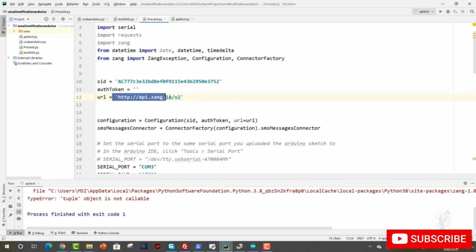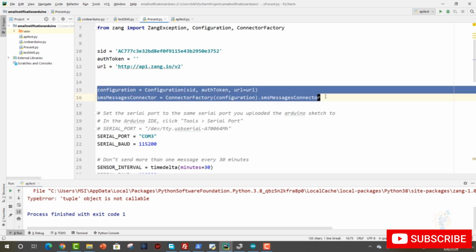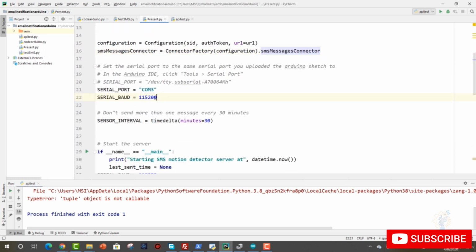The URL will remain the same, and these two lines are for configuration of the send SMS function from the API website. You don't have to write them yourself. Now here we have the serial port and the serial baud rate. We already mentioned that the baud rate will be 115,200, which is the same as in our Arduino code.